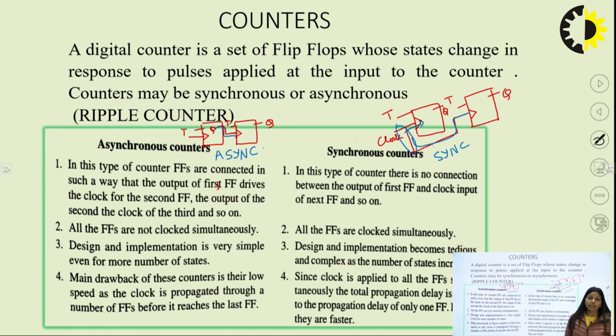The delay is more in an asynchronous counter and very little in a synchronous counter, right. Coming to the next part, let us design some counters using flip-flops in which one flip-flop is triggered by a previous stage flip-flop.